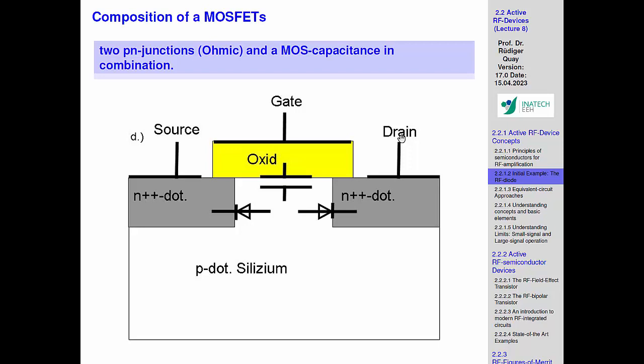And why is this off? Because you're making a doping profile here, and the stronger you pronounce the difference here, the stronger the diode isolates in this sense, unless you put it into a forward situation. And that is what helps. By the way, why do we dope the N regions very high? I think we had it last time. Why do we put so much high doping under the metal contacts at the source and at the drain? What is this idea?